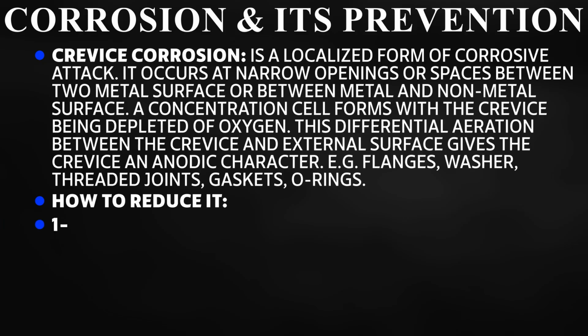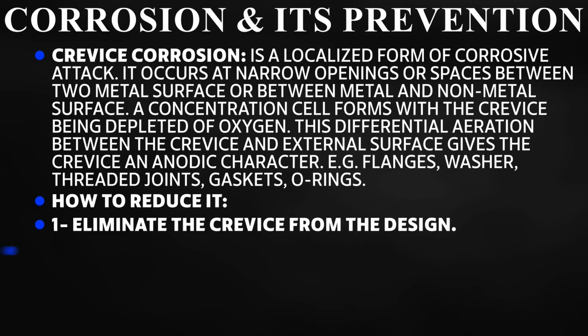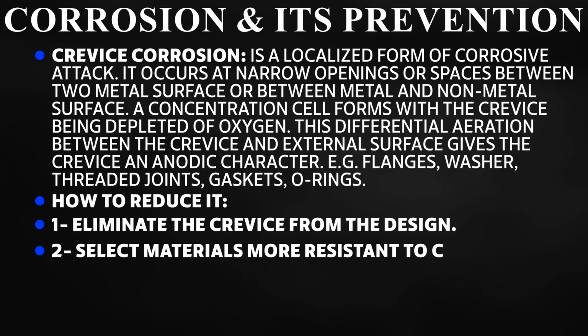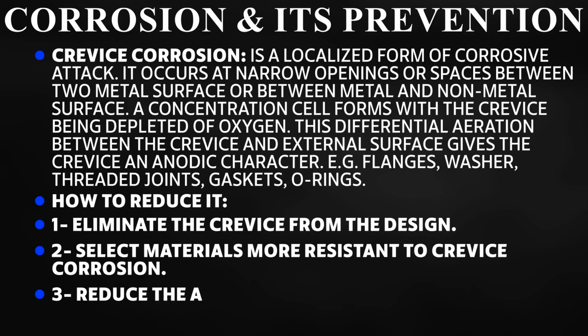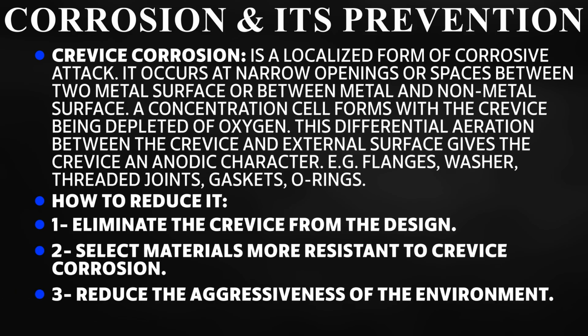How to reduce it? 1. Eliminate the crevice from the design. 2. Select materials more resistant to crevice corrosion. 3. Reduce the aggressiveness of the environment.